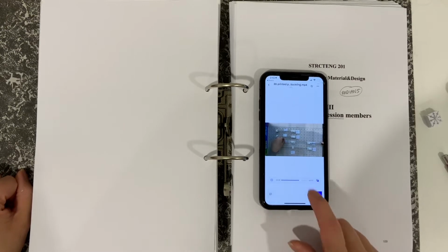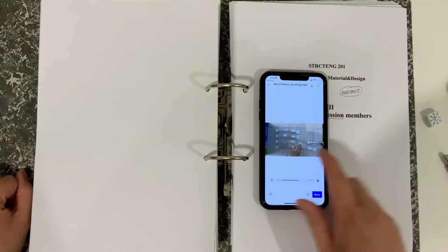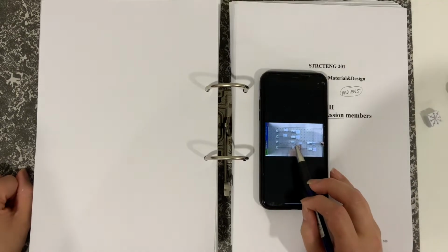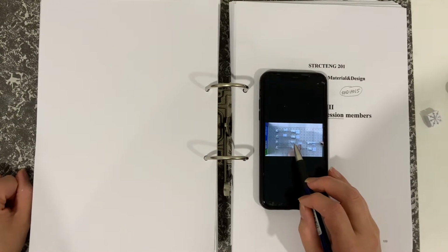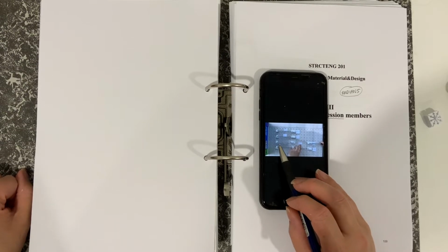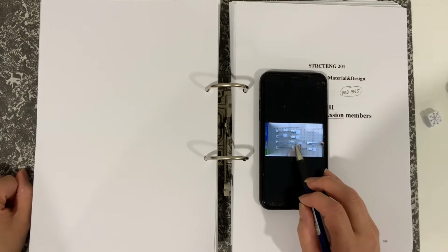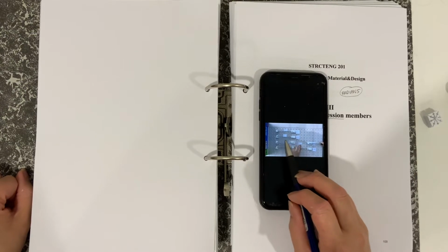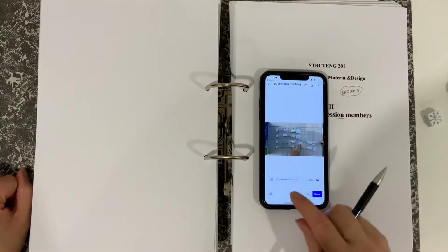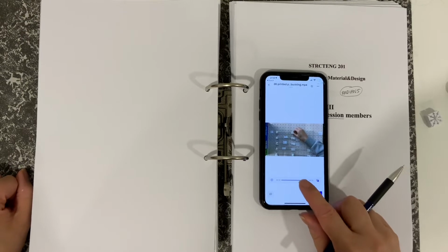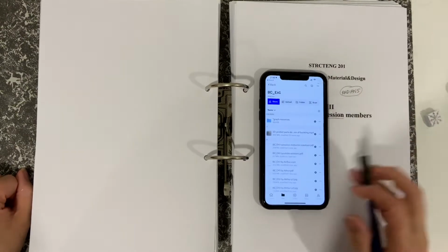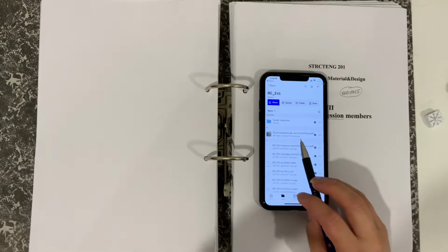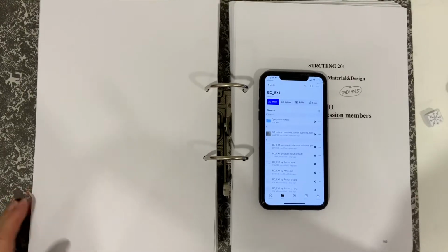If I pause that one there, you can see that having a restraint in the center, which is what that is, it buckles into two half sine waves. So it buckles into two half sine waves and behaves the same as that one there. You can have a look at the video if you wanted to, and it's in the Dropbox, called 3D printed parts demonstration of buckling.